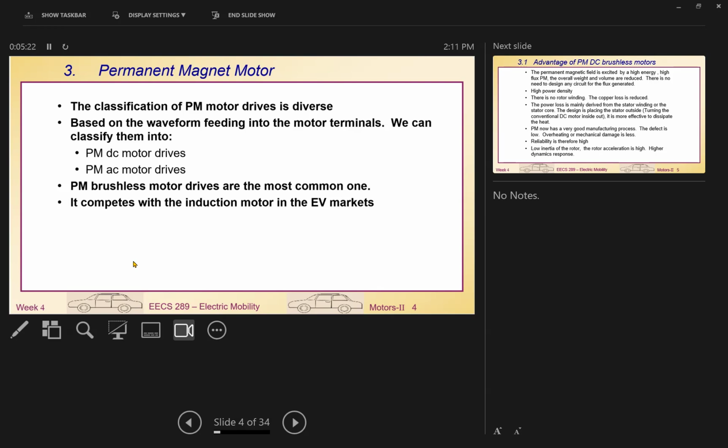Again, the PM brushless, like what we mentioned just now, you all like the brushless DC motor. It is also really common. But all the PM brushless motors at the moment we mainly see used in small vehicles, and also in the cooling system of your computer microprocessor, where the fans use brushless DC motors. It's very common. But for really, really large vehicles, like trucks and huge vehicles, we may have difficulty using DC brushless. Why is that?